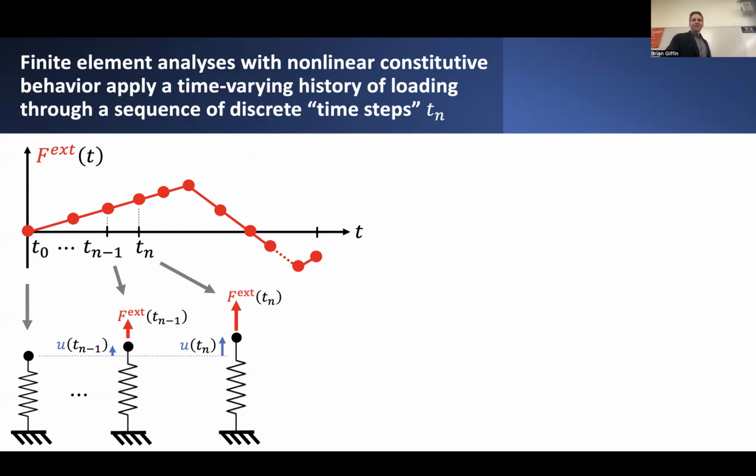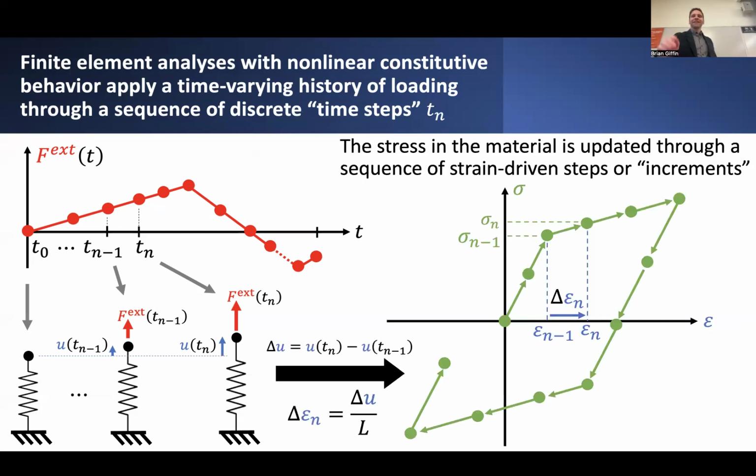So that's certainly true for certain types of materials, especially elastoplastic materials, where if you were to take, let's say, some uniaxial bar, which I've idealized as this kind of one-dimensional spring, and we subject it to maybe a few cycles of loading, you can see that the relationship between the strain in the material and the resulting stress in the material might exhibit this kind of nonlinear envelope.